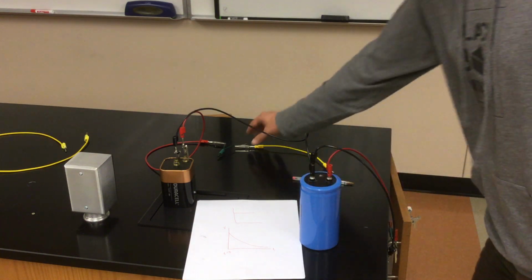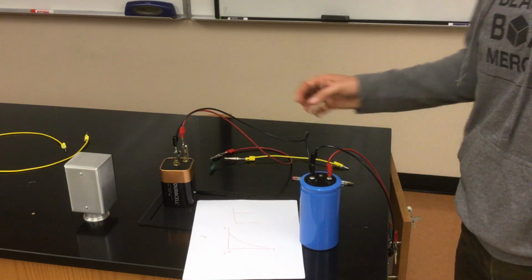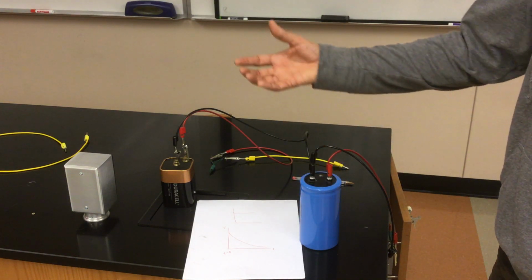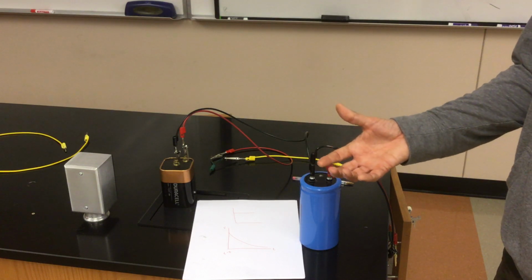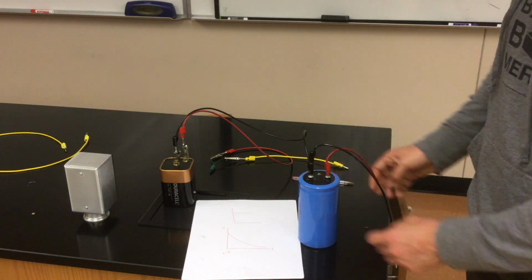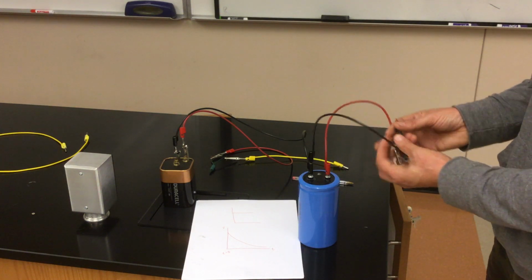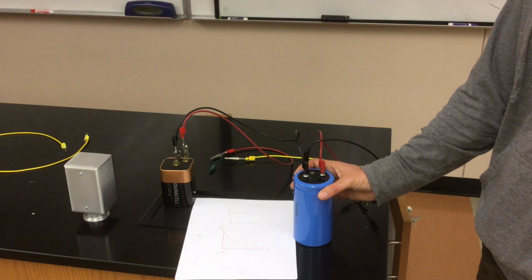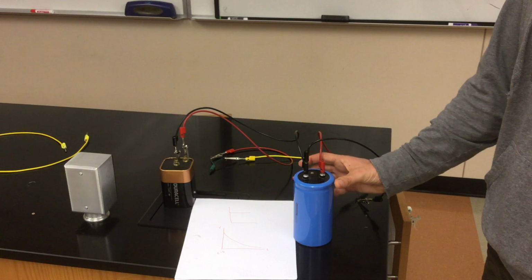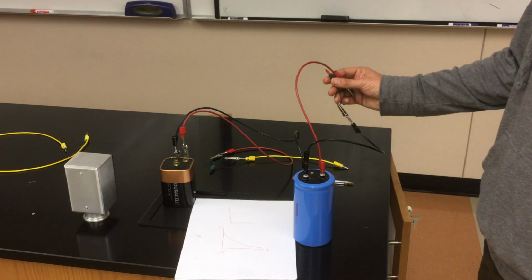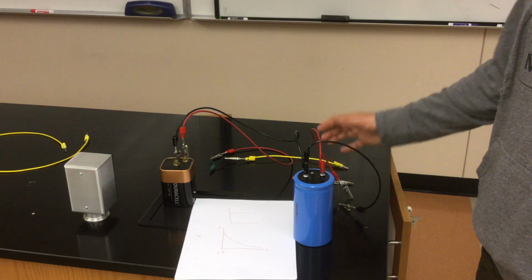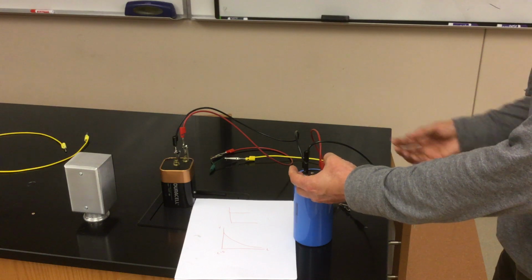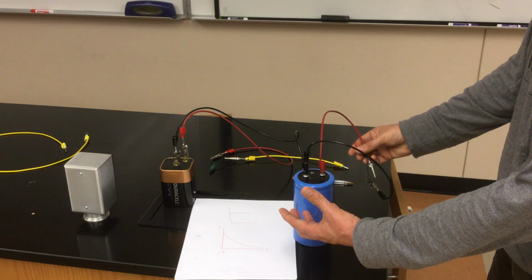So that gives another practical application for capacitors in electrical circuits. When capacitors are combined with resistors, there's a certain time delay for which the electricity fades away to being practically zero value. It depends on the exact value of the capacitance and the exact value of the resistance. But in any case, that's a second function of capacitors in practical application. They're not just there to deliver a sudden burst of charge when you need it, but when the current is run through a device that resists the flow of electricity to some degree, the time delay can be controlled by the combination of how much resistance and how much capacitance. Pretty neat.